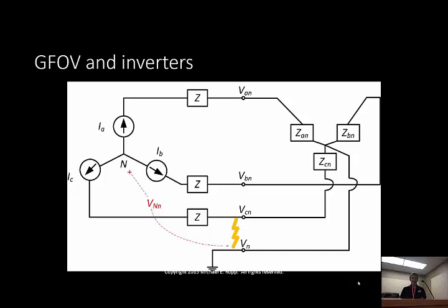Now we're going to look at a case that has an inverter in there. And you see the same three-line diagram. The inverter, again, is not grounded. And I should point out that, I think I might have mentioned this before, generally speaking, inverters aren't grounded. They do appear as three-wire sources. So the concern was definitely a valid one, at least at first. We started investigating this.